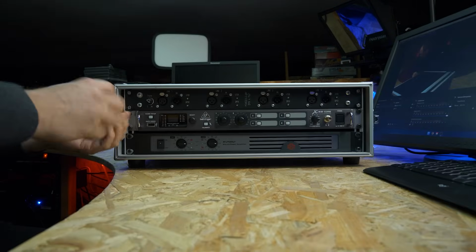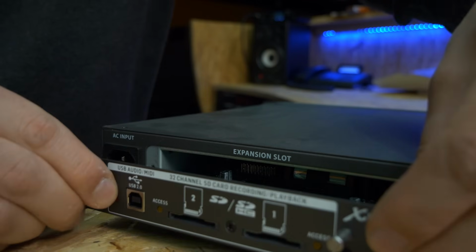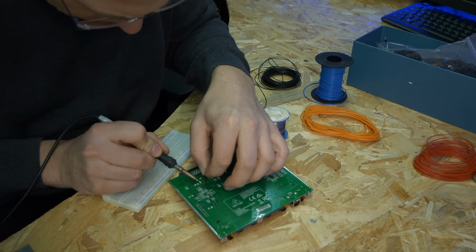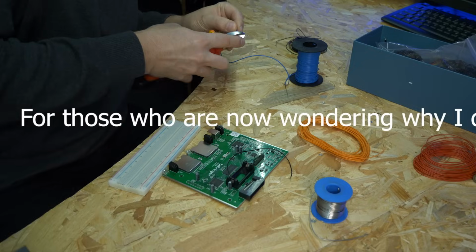We therefore need the functions of the XUF or XUSB and then later on those of the X-Live. Unfortunately, it is only possible to view the individual signals when the card is installed. So I have to solder test jump wires to the card and install it inside the X32. I prefer to use my X32 core here. In the case that I break something, the damage won't be as bad as with the full-size console.